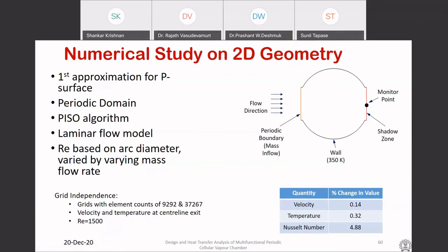We assume that gravity has no role in it because the flows are very fast. At some point, as you keep increasing the velocity, this separated zone starts to interact with the main flow, because that main flow is shearing the flow that is sitting here. After some point, it starts to shed vortices into the mainstream. So that is the start of this unsteadiness. That vortex keeps shedding, and there is a core flow, and I'll show some pictures too.